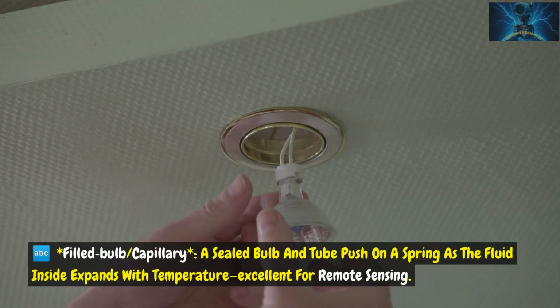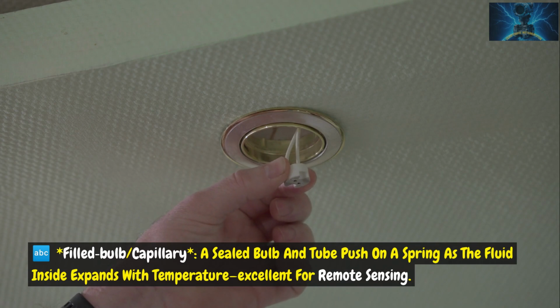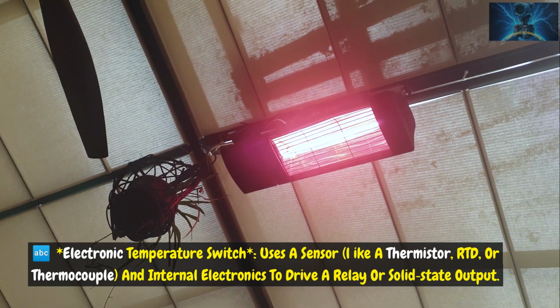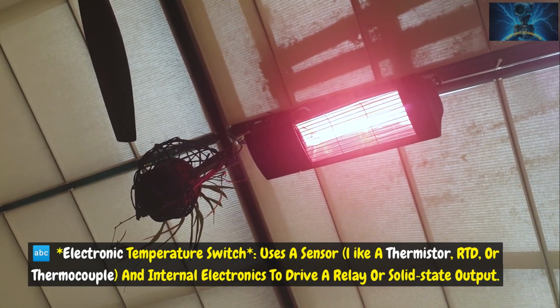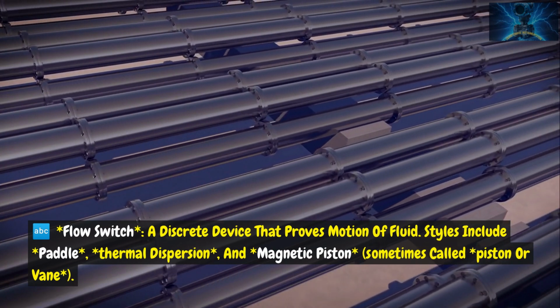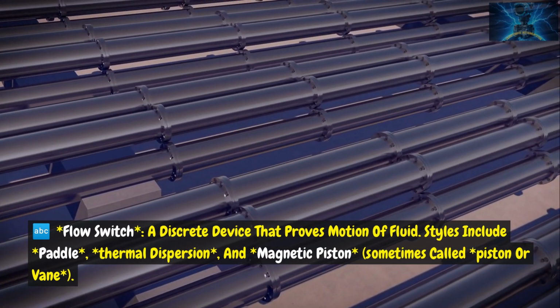Filled bulb, capillary: a sealed bulb and tube push on a spring as the fluid inside expands with temperature. Excellent for remote sensing. Electronic temperature switch: uses a sensor, like a thermistor, RTD, or thermocouple, and internal electronics to drive a relay or solid-state output. Flow switch: a discrete device that proves motion of fluid. Styles include paddle, thermal dispersion, and magnetic piston, sometimes called piston or vane.